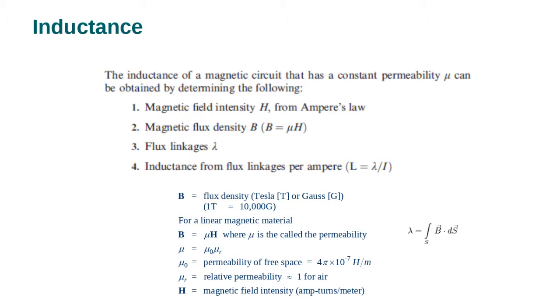And then we mentioned conductance G on the transmission line. When we represent the transmission line, we represent it as resistance and conductance. Conductance means in shunt. There is a resistance connected in shunt. What does it represent? It represents the leakage current through the insulators, because the insulators will get dusty.